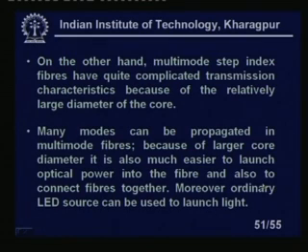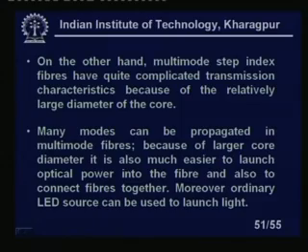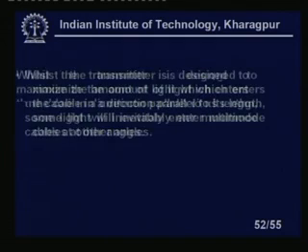Many modes can be propagated in multimode fibers because of the larger core diameter. It is also much easier to launch optical power into the fiber and to connect fibers together. Two fibers can be easily connected together. Moreover, an ordinary LED source can be used to launch light. That is most important. I do not need a laser.